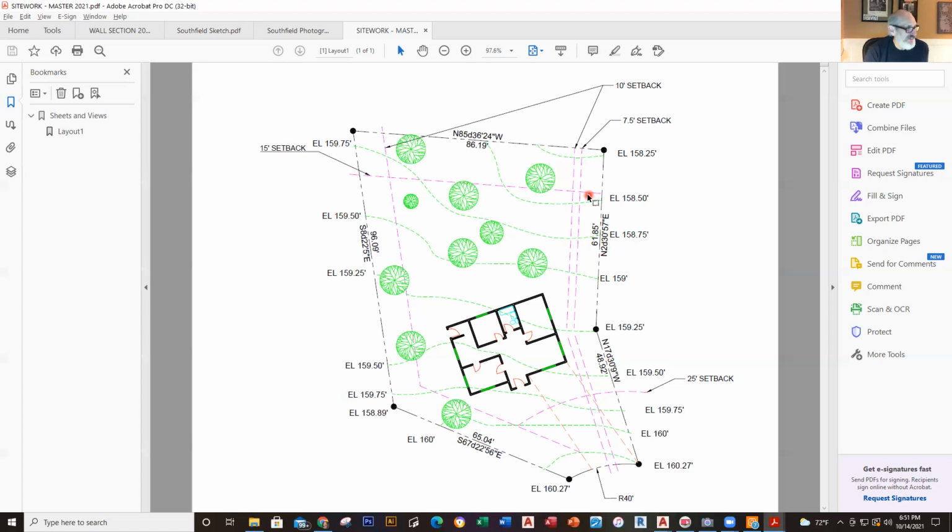Typically, in most municipalities, you're supposed to leave like a 6 foot distance between the property line and your fence. It varies from municipality to municipality. Sometimes it's 2 feet, sometimes as much as 6, sometimes it's less. Now that's for a fence. The structure is something totally different. You typically can't crowd the actual space. So there are setbacks, and these are basically declared by municipalities, and that then gives you the area that you can actually use for building.